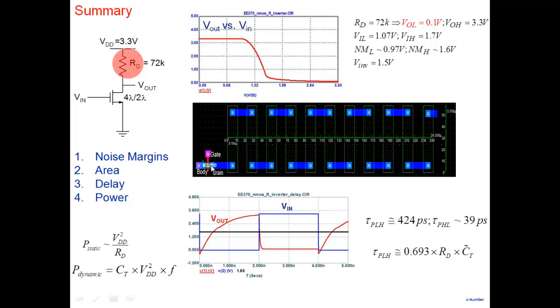Because note that the transistor is over here. I can easily increase the size without too much area penalty. And if the resistor size comes down, then the overall design becomes better. So now, if I increase the size of this particular transistor, we are saying resistor size will come down, area will become smaller. Anything that I lose by making the transistor bigger? Suppose you accept that if I increase the transistor size, RD will come down. So area will come down.